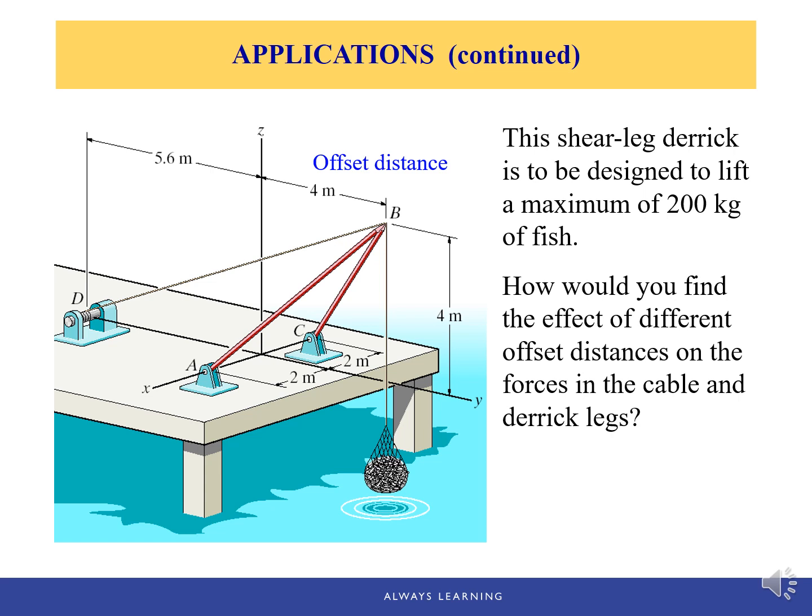We also see some simple design questions. Maybe you're asked to find the maximum weight that can be suspended by the structure, or sometimes you may be asked to find a certain distance to make sure the structure is safe. But overall, again, the key point here is the assembly is no longer just within the XY plane, but now you have a three-dimensional problem. And that's the topic for this class, 3D particle equilibrium.